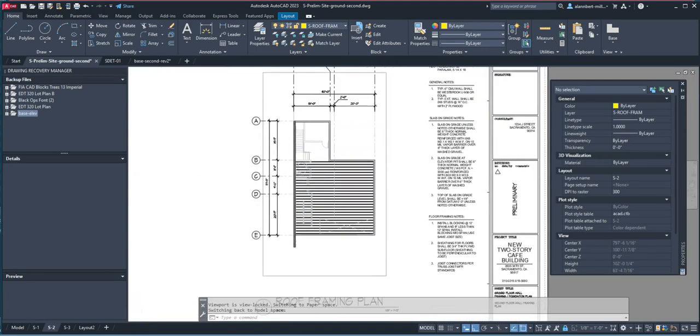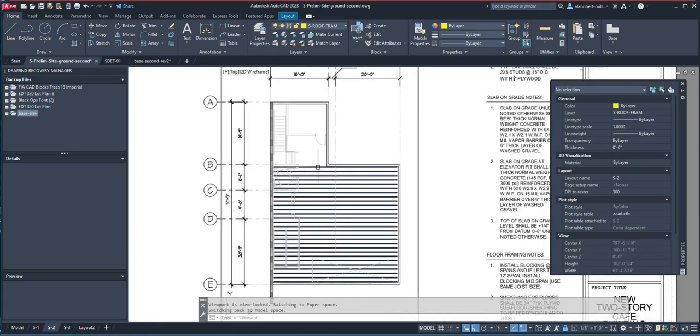Now, although this spans shorter, we may switch to a different depth here. This one's all 36 inches. The problem with switching to a different depth is you would have to build the wall higher on this side, which is fine. You can build the wall higher.